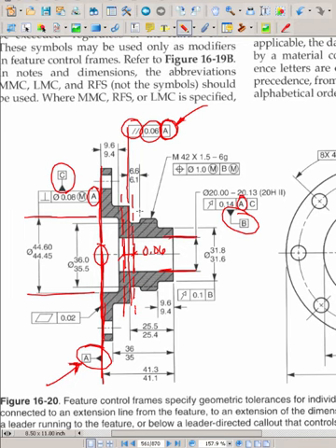Okay? Clear as mud yet? Well, we're going to get more into it, and you'll learn more as we go along. But that's how you basically break down any geometric tolerance. First, check out where your datums are, then check out your tolerances.